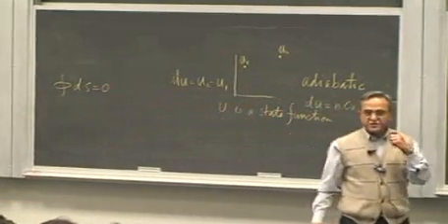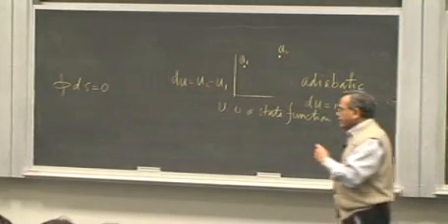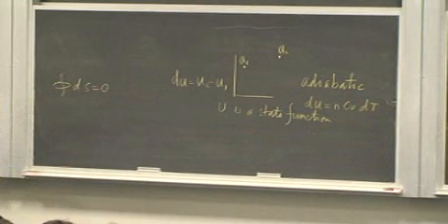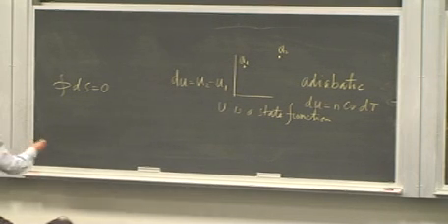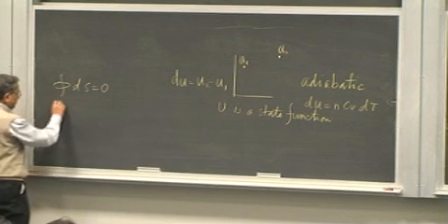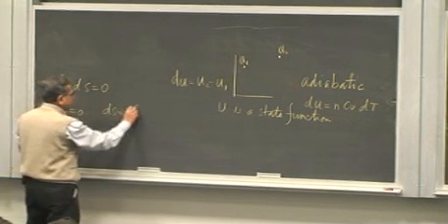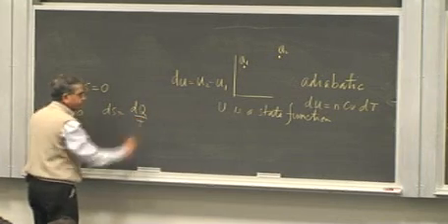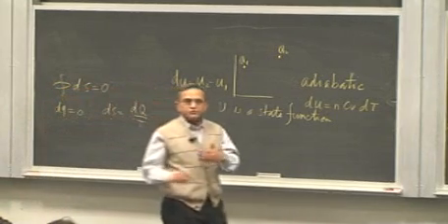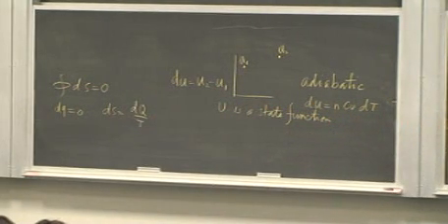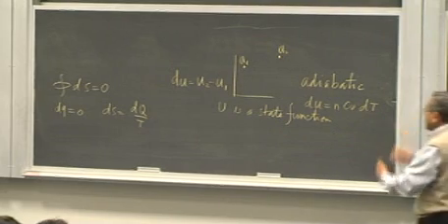Change in entropy doesn't depend upon paths, and we were faced with a situation where we were looking at an adiabatic process, and in an adiabatic process dQ is equal to 0, whereas dS was defined as dQ over T, and we didn't know how to get the value of change in entropy in an adiabatic situation.